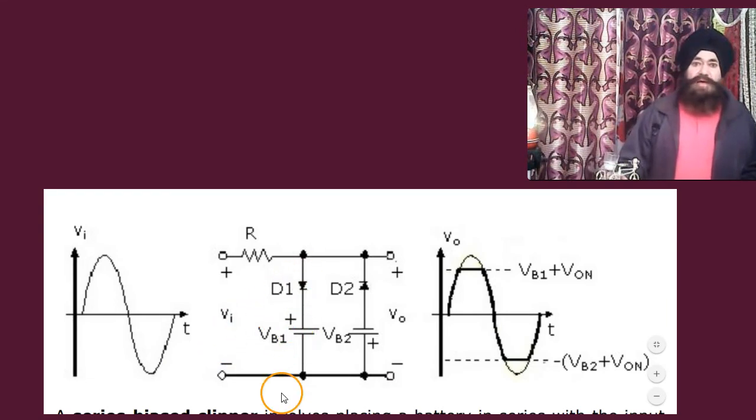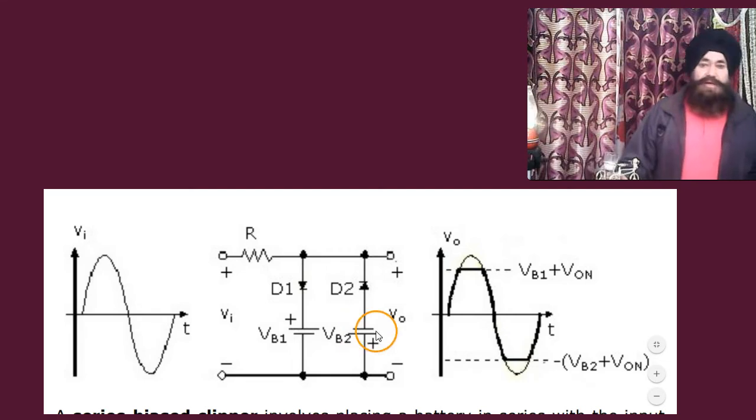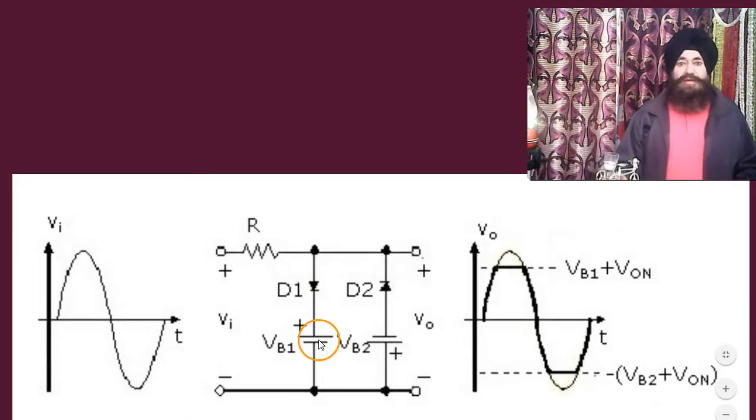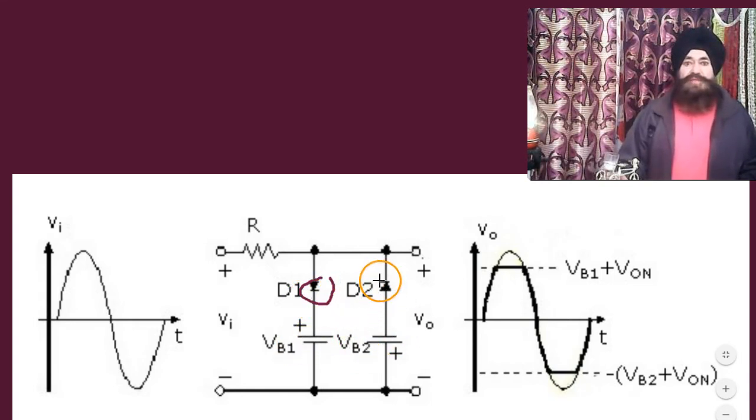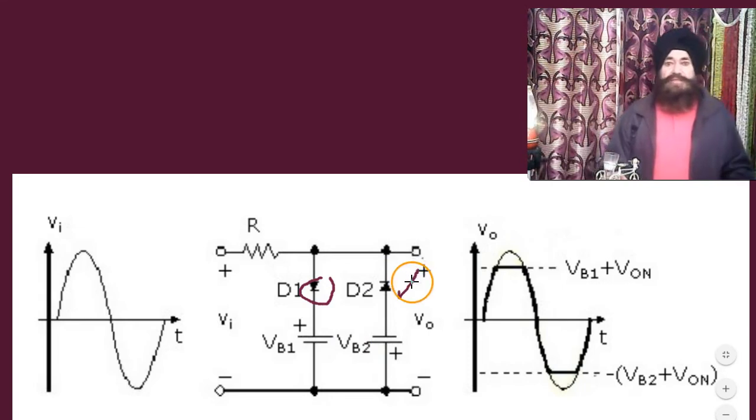Now, again the ideal diode and double clipper circuit. So there are two lines here: battery positive-negative, and here negative-positive, and this battery is making this diode reverse biased, because positive is here and negative is there. This battery is making this diode reverse biased.